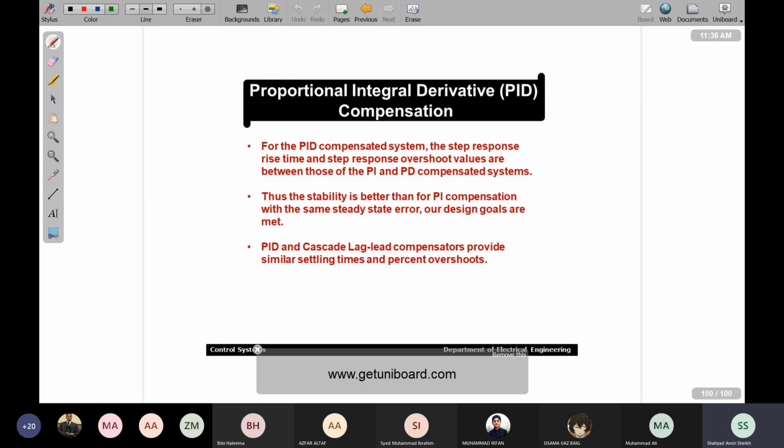The design parameters are of course K, A, B, because K is the same proportional constant, but A and B are the locations of zeros and poles, and in order to design this controller or compensator, you have to know where you have to place your zeros and poles. In that context we discussed the value D, we defined a ratio parameter, which is in fact A divided by B, and we have said that A is greater than B. In that case D will be greater than 1.